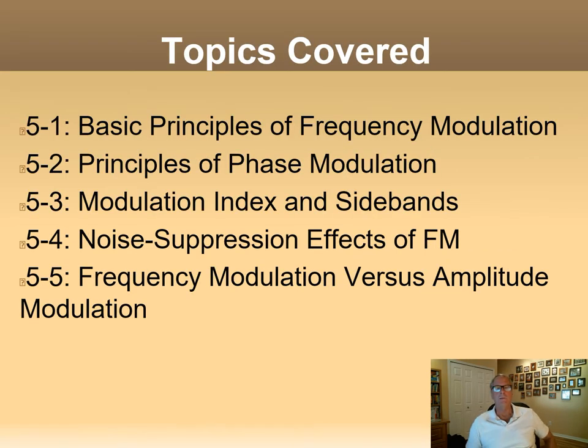So what we're going to talk about is some of the principles of FM, frequency modulation, the principles of phase modulation, which is very similar. It's almost difficult to distinguish the two. Just like with AM, there's a modulation index and sidebands associated with FM also. We'll see how FM has better noise suppression characteristics than AM, or I should more accurately say immunity to noise. And then we'll look at the differences between FM and AM.